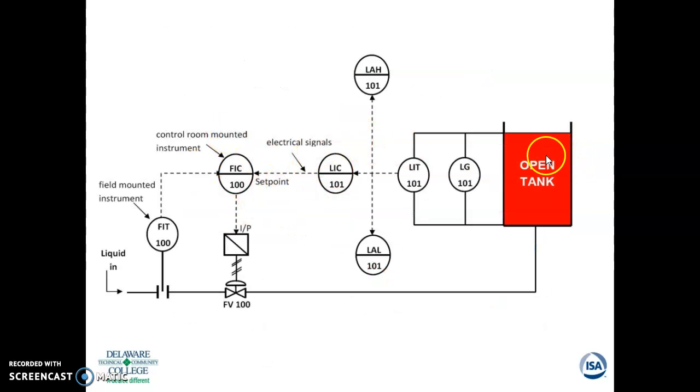Okay, here's the final one. We're looking at an open tank, a level gauge, and a level indicating transmitter 101. They're all 101. It's feeding information to the controller, again, electronically. Electrical to the FIC, the flow indicating controller. And then the transmitter comes over here and is fed to that. The set point sets that flow to tell the controller what to do. Another electrical, I to P. Over here, current to pneumatic, pneumatic to your control valve. So straightforward flow. Again, this is a cascaded loop.